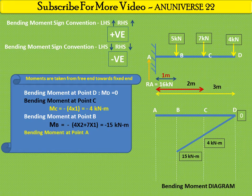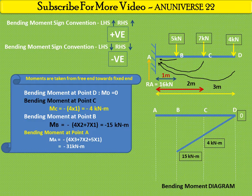Now the bending moment at point A. For calculating it, all the point loads acting at B, C and D move towards point A. First the 4 kilonewton load covers a distance of 3 meters, so 4 into 3, negative. The 7 kilonewton load covers a distance of 2 meters, so 7 into 2, and the 5 kilonewton load covers a distance of 1 meter, so 5 into 1. All these values are negative because they act in the downward direction. So the bending moment at point A is negative, 4 into 3 plus 7 into 2 plus 5 into 1, equal to minus 31 kilonewton meter. On the bending moment diagram, the line from 15 kilonewton meter goes up to 31 kilonewton meter.